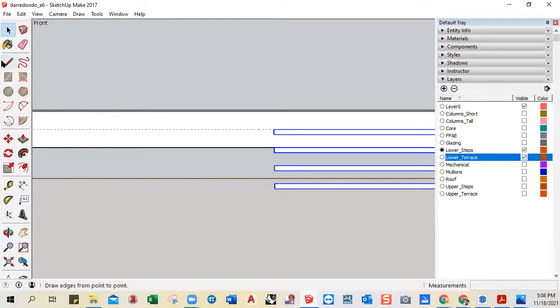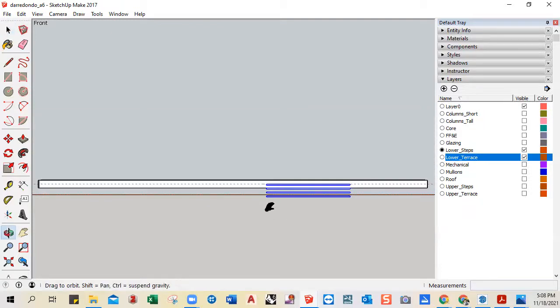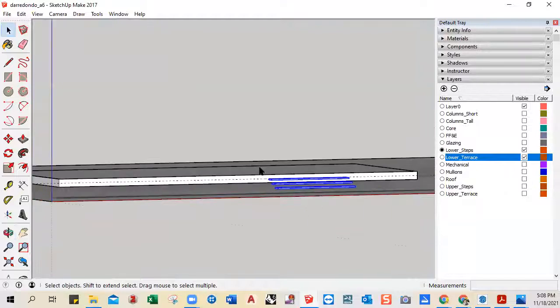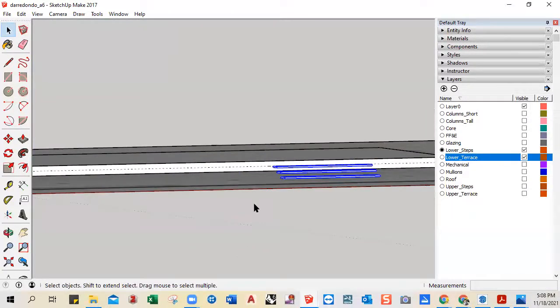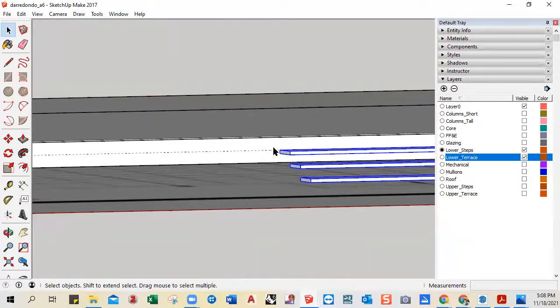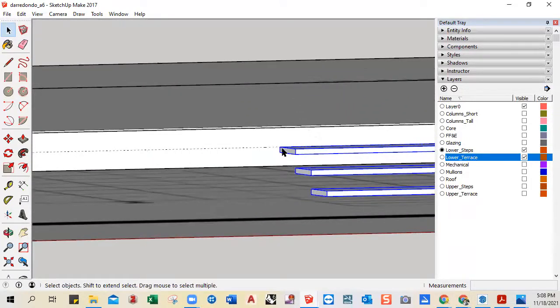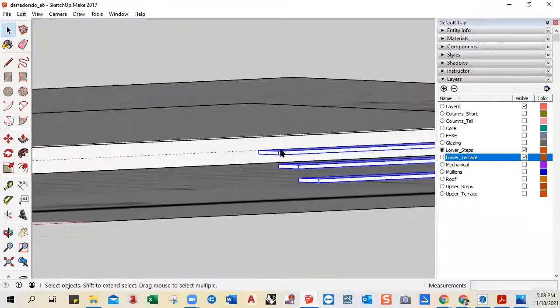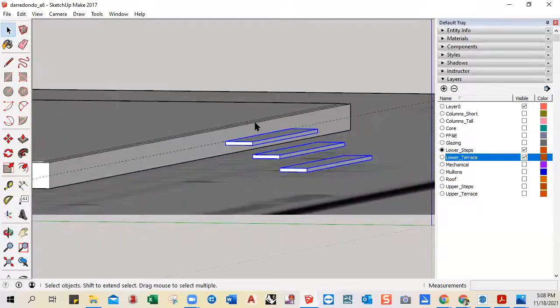Okay. And this is 2 inches. It looks like it's off by about 2 inches. It's not a big deal, but you know, we want to make sure we do things right. Okay. Now that we have that and the distance is correct, right? Our dimensions are correct. We're 7 inches from here and 7 inches from this, the top of the step to the top of the step, from the step to that step, and the top of this one to the other, which will avoid any tripping hazard